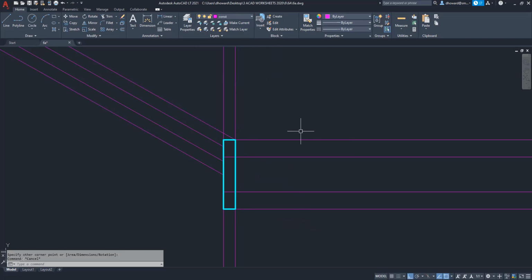We can offset, right? So going back to my construction layer, I'm going to make a construction line, XL, enter, A, enter. And I need to make a perpendicular line to this guy, all right? So that guy was at 150. So if I'm going perpendicular to that, going backward, 150 minus 90 is 60. No big surprise. So the angle is 60, and I'll click it right there. All right, so now I've made two angled construction lines. These ones heading off toward the left were at 150, and this guy heading off to the right, perpendicular to them, is just 60.